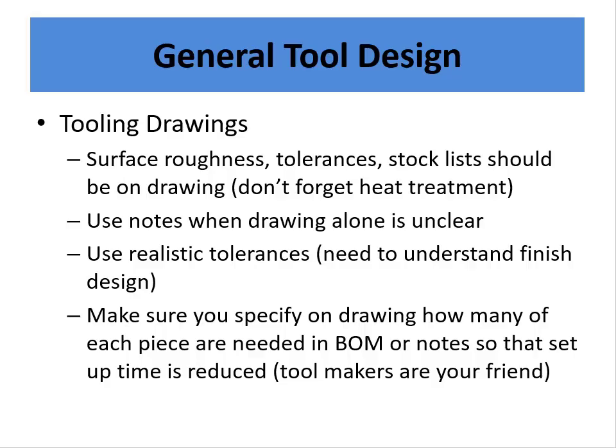And then you're also going to want to, again, this is kind of repeating, but use realistic tolerances. And that depends on what you're doing. If you work at a company that's making gauges, you're going to have different tolerances than a company who's making parts to hold something. If you're making Nerf guns or something like that, maybe the tolerances in some areas are really tight. Actually, probably some of those things snap together with really tight tolerances. I know Legos are extraordinarily tight tolerances, believe it or not. But some other things like that, if they're not critical, they're not going to be so tight tolerance. So you need to really understand what matters where.